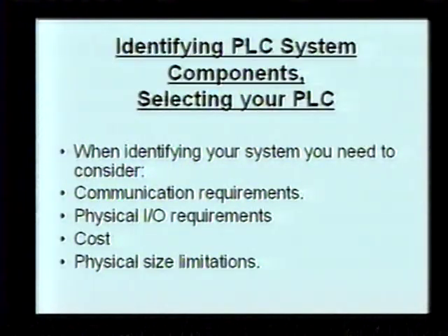Next, we're going to identify PLC system components, selecting your PLC. When identifying your system, you need to consider the following. What are your communication requirements? What are your physical I/O requirements? What is your cost? How much money do you have in this budget? And your physical size limitations.